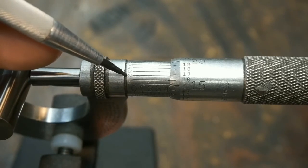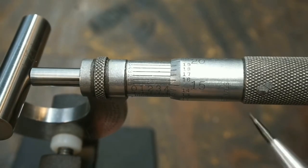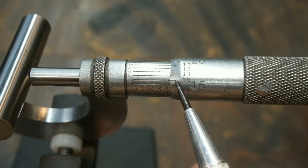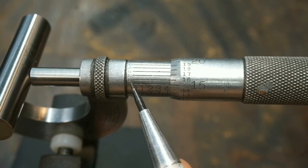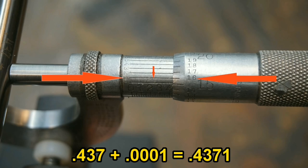0, 1, 2, 3, 4, and it goes all the way around to 9. And if you'll look over here, this number 16 is perfectly in line with that number 1 line right there. So this is 1/10. The one after that would be 2/10, and you can see it's slightly off. Okay, so I'm going to call it 16 as being the one that's lined up with the number 1. So we are at 0.4371, the 1 being the 1/10.